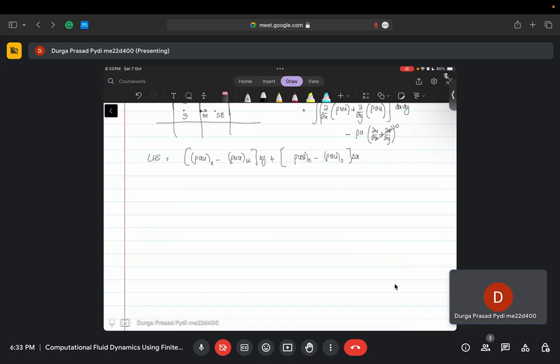So it's non-linear, so we will not be able to solve it as it is in this particular way. So we have to linearize it. What we do is use a scheme like the deferred correction approach. We just assume rho u, taking the value of u and v from the previous iteration. What I was trying to say is rho u east times u east,